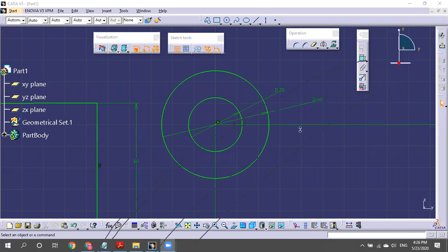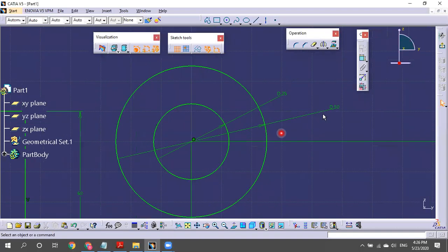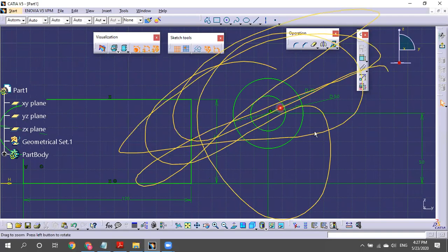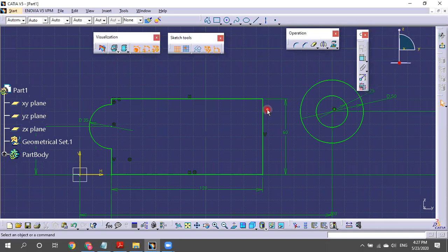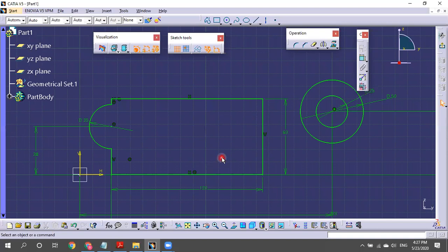Perfect. So now what we are doing, we understand that this is the best practice of creating. The first thing is that you need to understand when we start building the sketches, the sketch should be fully constrained, and for fully constrained sketches, it should be fully green color. That fully green means you need to understand that the sketch is fully constrained. Okay. So any doubts so far, gentlemen?